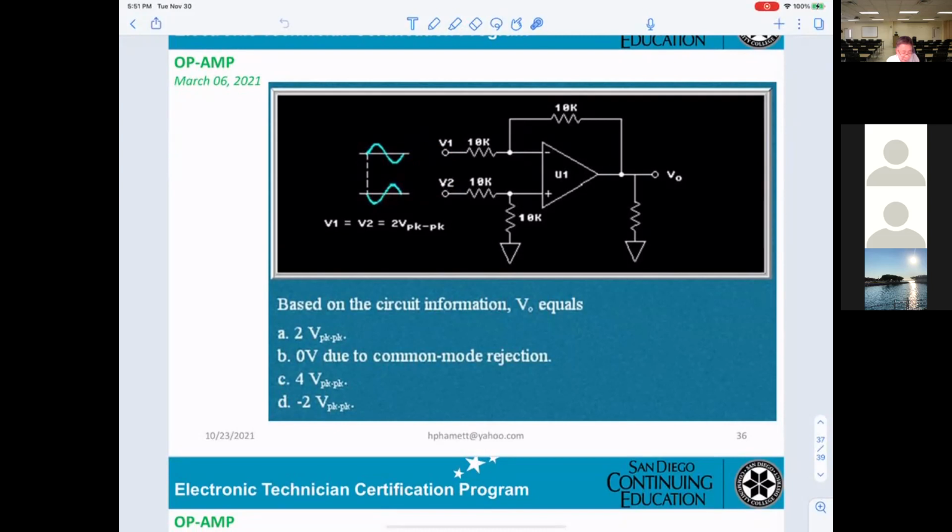But with that 2 volt applied, you have to know what the voltage is here for the non-inverting input. V2 is not a direct input, it must be connected directly to the positive. So basically, at this point you get 2 volt here, then at the point right here, 2 times 10K divided by 10K, you get 1 volt. Okay? So this is 1 volt.